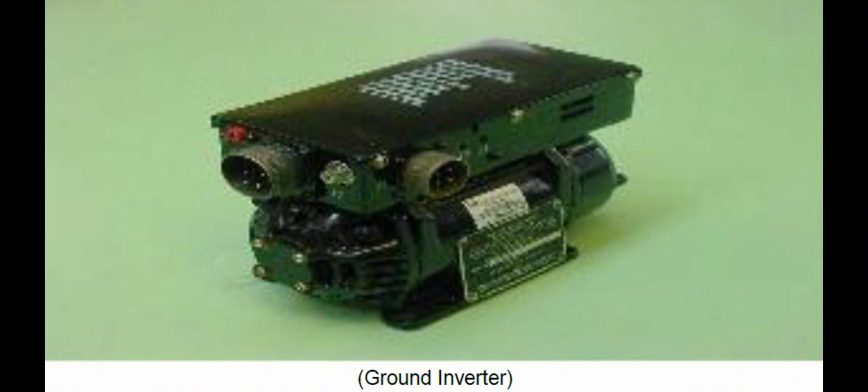Inverter control relays. Inverter control relays are located on the number 1 relay panel on the left attic compartment shelf. The relays are 2-pole double-throw contactor relays. When the relays are de-energized, normally closed contactors provide a DC voltage path from the inverter control switch in the on position to the solenoids of the inverter transfer relays. The inverter transfer relays in turn allow power to be applied to the inverter and connect inverter loads to the inverter AC output. The path from the solenoid of the number 1 inverter control relay is routed through the contacts of the closed inverter control switch to the number 1 primary bus and the path.